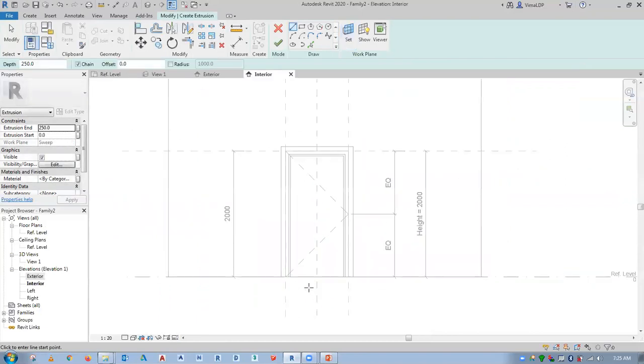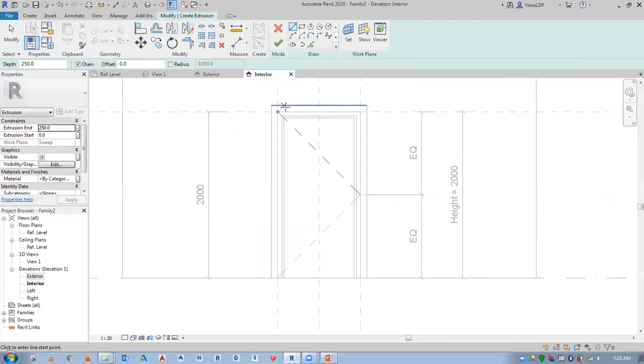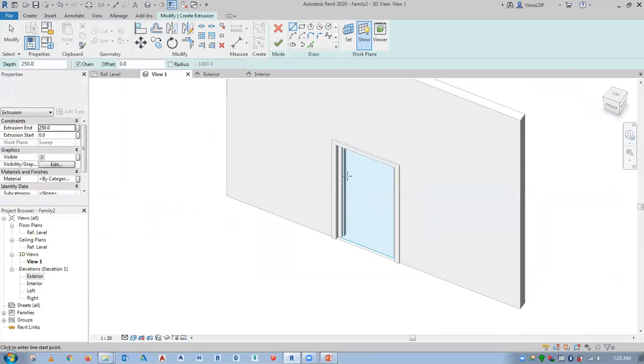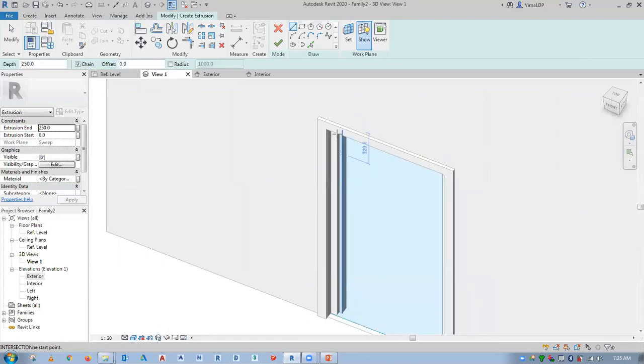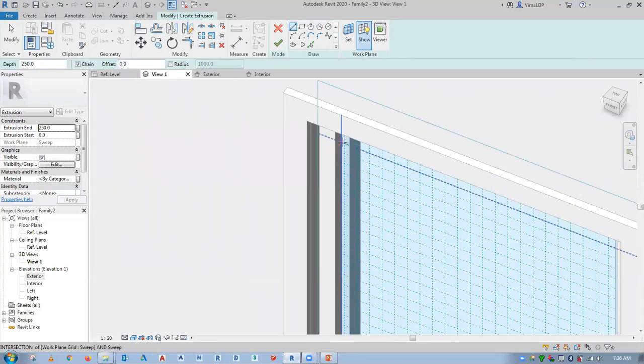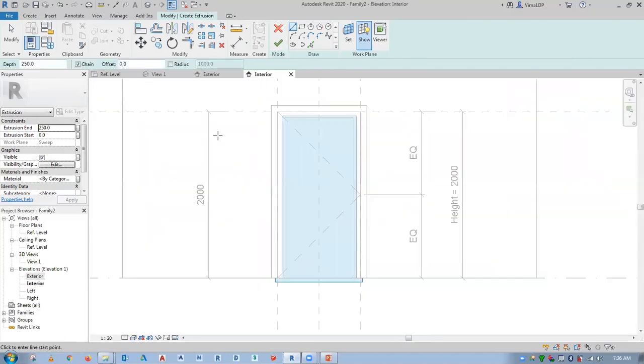So I know that these are my architraves. These are my frames which I have created now using the sweep. Now I need to know where I'm going to sketch. So if I just click on show, it shows okay, this is the plane which you have specified or selected. And in your 3D views, you can see the plane is actually on the face of the stopper. Okay, that's pretty much the correct location. Let me just say I don't want to see the frame for now.